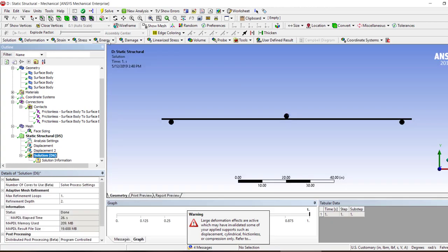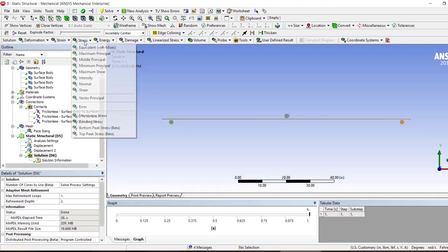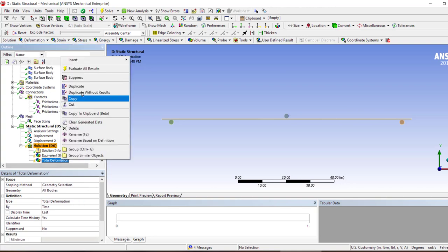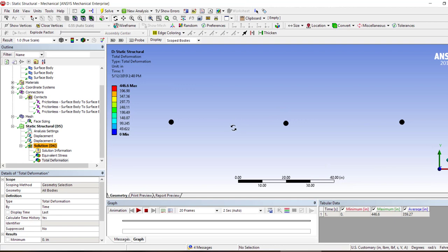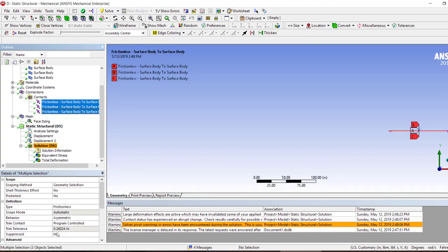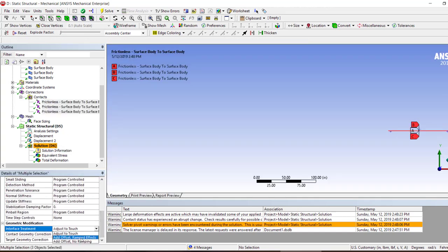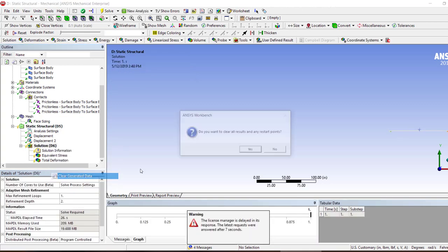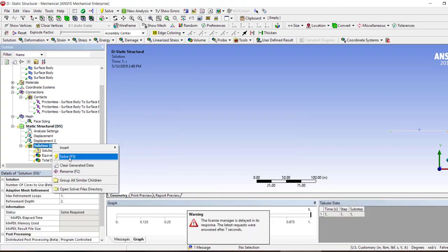Wow. So let's see the stresses, or deformation would be most important. Yeah, the contact never established, so it's gone somewhere. And we can see this thing 446 that was there as well. So let's try and change the contact to be ramping, and then we try it again.